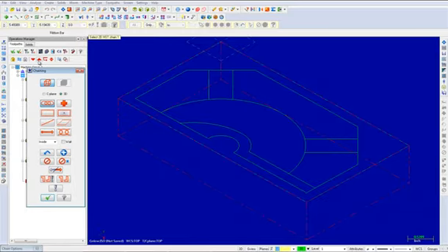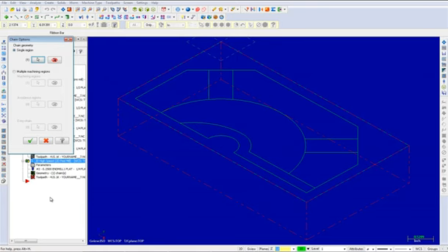When the chaining dialog box appears, leave the default settings and choose the following line. Once the geometry has been selected, choose the OK button to exit the chaining dialog box. Again, choose the OK button to exit the chain options.